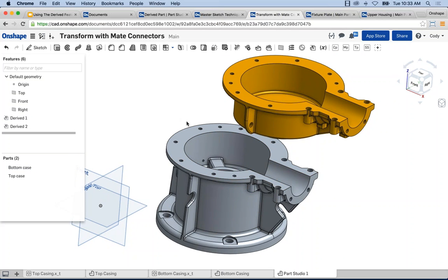But in complicated scenarios, or just scenarios where I want to take this and attach it to this, mate connectors seem to be the easiest approach. Now, another tip that I have is I would recommend inserting the mate connectors at the original tabs for the imported models in my example. This is just so that if I insert these parts anywhere else, they also come with that mate connector. It just makes it easier to do this again anywhere else.